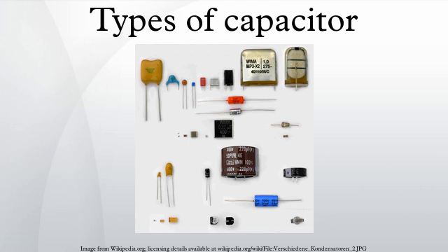In the data sheets, the AC load may be expressed as rated AC voltage at low frequencies, rated reactive power at intermediate frequencies, reduced AC voltage or rated AC current at high frequencies. The rated AC voltage for film capacitors is generally calculated so that an internal temperature rise of 8 to 10 degrees is the allowed limit for safe operation. Because dielectric losses increase with increasing frequency, the specified AC voltage has to be derated at higher frequencies.